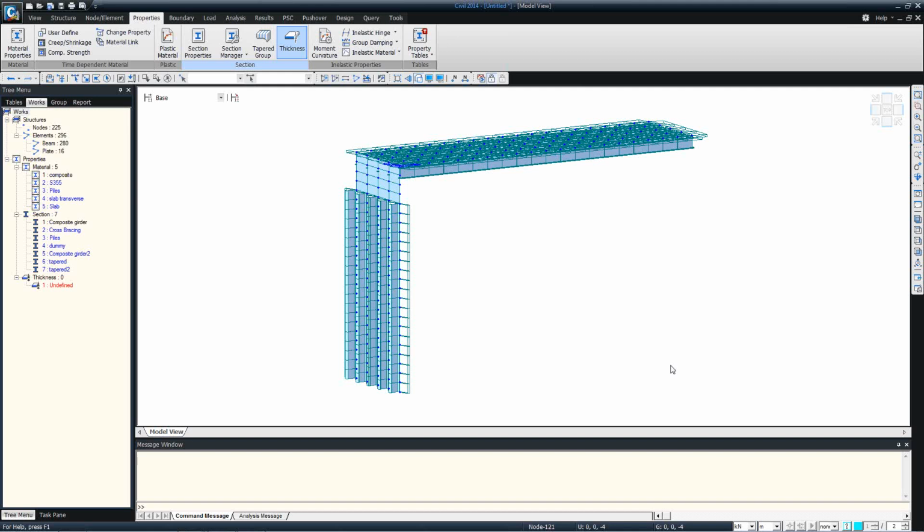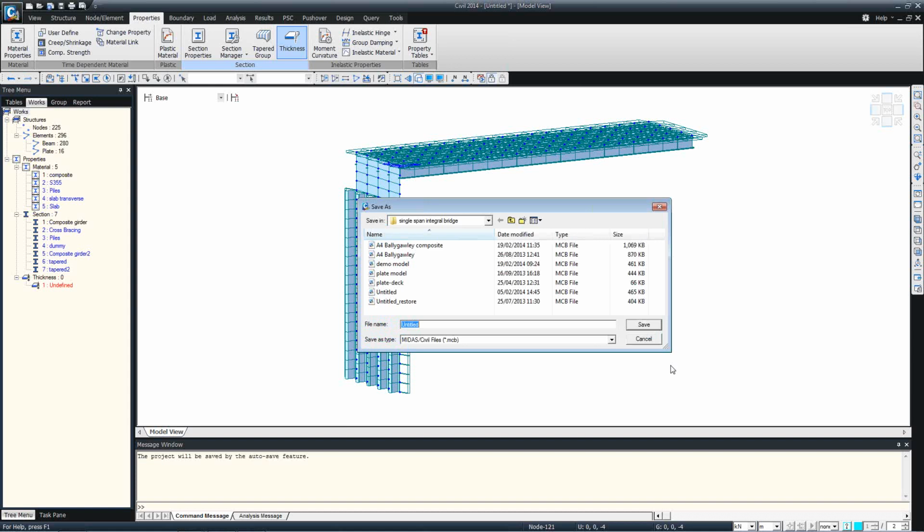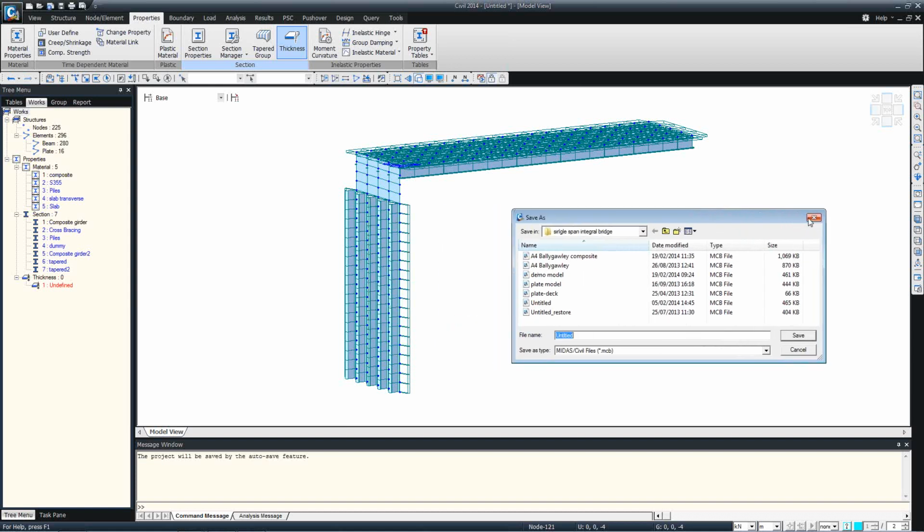Sometimes you can also use polylines, but I would not recommend using polylines every time, because polylines can have some problems with the intersection. It is always good to use lines whenever you have to generate arcs or any other type of geometry.